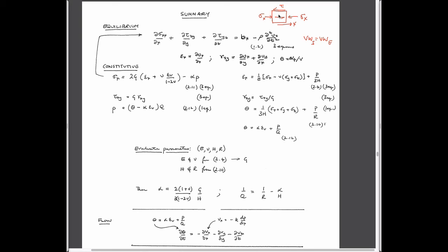So you have a force pushing in this direction. If the force that I'm applying with my left hand is less than the one that I'm applying with my right hand, then there has to be some shear stress applied on here and some shear stress applied on here to keep it in place. And the physical explanation of that is that the stress in the x direction, as it changes from my left hand to right hand, has to be directly balanced by the changes in shear stress as they go across on those two other faces. So that's the reason why there's these three terms.